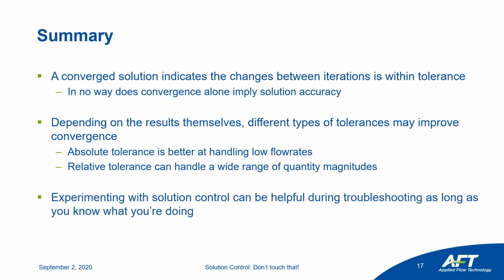And so finally, experimenting with solution control can be helpful during troubleshooting. But again, you have to know what you're doing. You have to understand the consequences, know that convergence does not mean accuracy. And in most cases, you should just rely on the default.